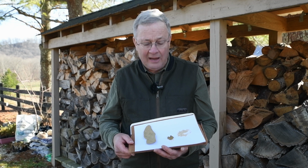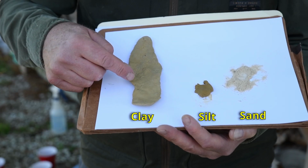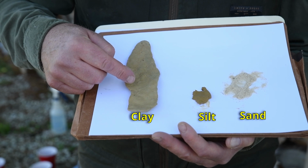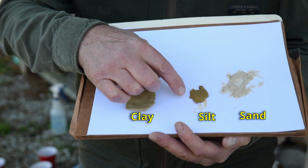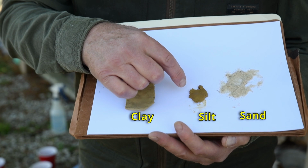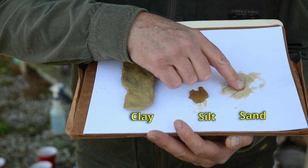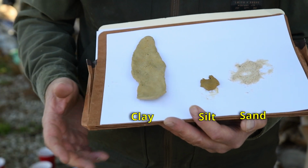So in looking at these samples here, here's clay. Notice I was able to make a 6-inch long thin ribbon from clay texture soil. But here is silt. My long thin ribbon is only 1 inch. That's pretty short. And then here is sand. I was not able to make a ribbon out of sand. What does that mean for building a spillway?